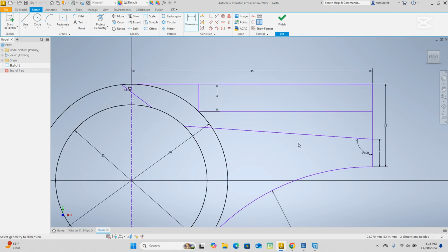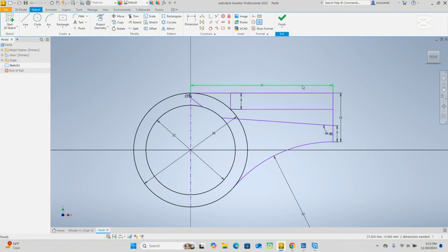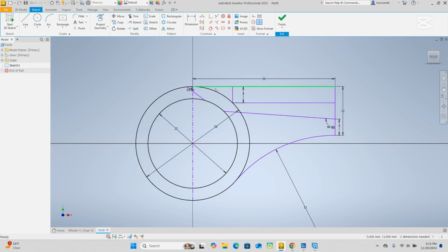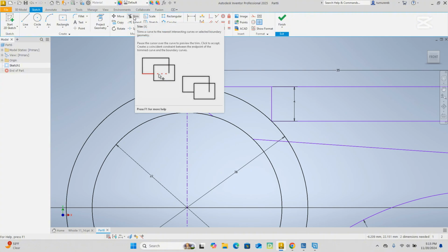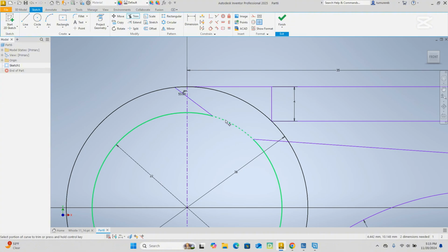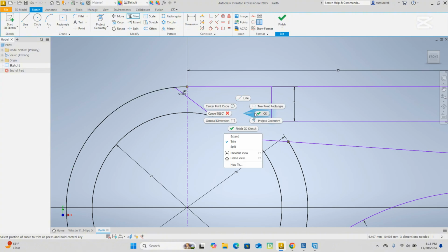Now, what does this look like? How are we gonna make this thing a whistle? Anybody see a whistle shape already? Let's look at another powerful command. Trim, my friend. It's the trim command. Trim is like a delete command, but for a selected area. So we don't need this part. Go ahead, trim that out. Also trim this part out and this guy out. Boom.